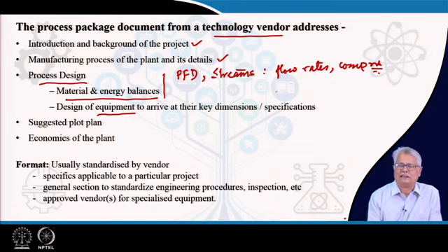Overpressure due to expansion of any trapped liquid is taken care of by a thermal safety valve. This is something which we have talked about when we talked about heat exchangers. I will just give you an example. I have here a shell and tube exchanger, and what I have here are two gate valves which are isolation valves.